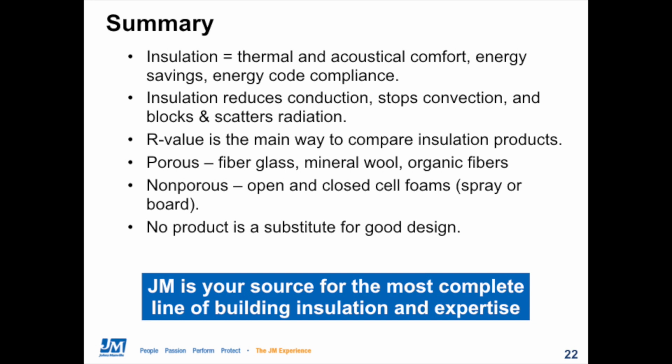Okay, thank you. Is AP foil an alternative for XPS on below grade applications? Yes. Historically, there have been many various papers and pieces claiming that polyiso shouldn't be used below grade. And I know here at Johns Manville, we've been working pretty hard over the last 10 years or so to try to refute a lot of that. What we have found is that polyiso can work in below grade applications every bit as well as XPS can. We haven't seen any examples where it shouldn't be used that way.